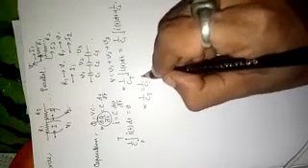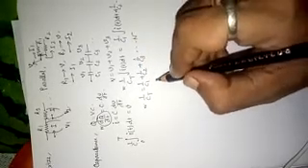From here you can integrate, getting the integration of i dt from 0 to t into 1 by C equals to V. Finally, 1 by C total integration of i dt equals to 1 by C1 integration of i dt plus 1 by C2 integration of i dt, and in this way it comes as 1 by Ct equals to 1 by C1 plus 1 by C2 plus 1 by C3, for n times. This is the series combination.